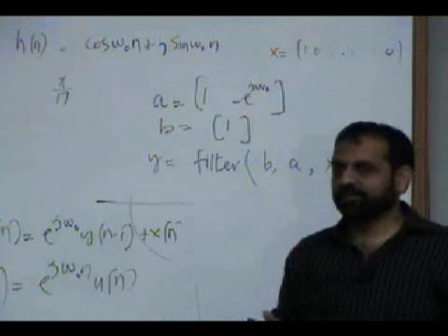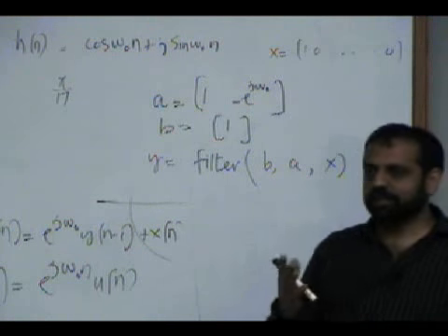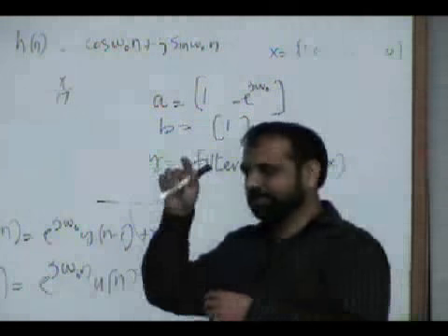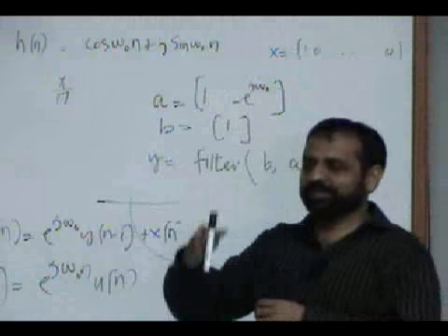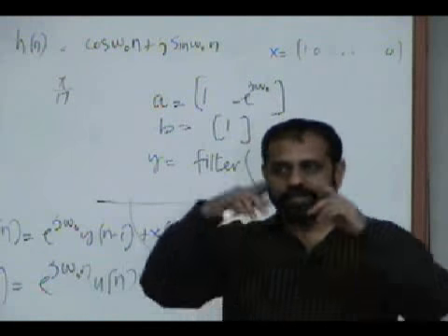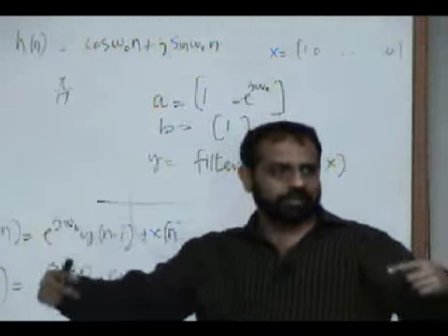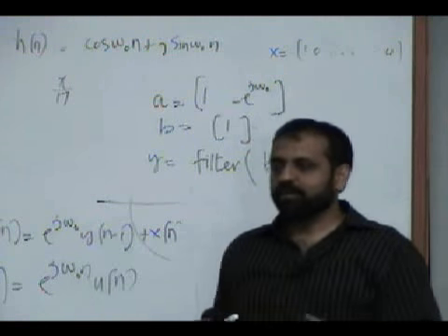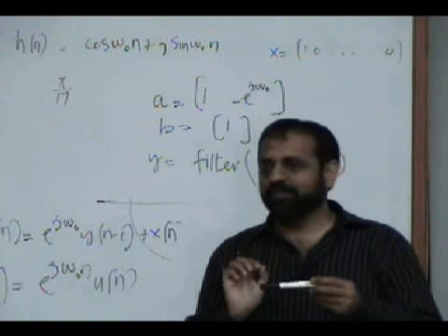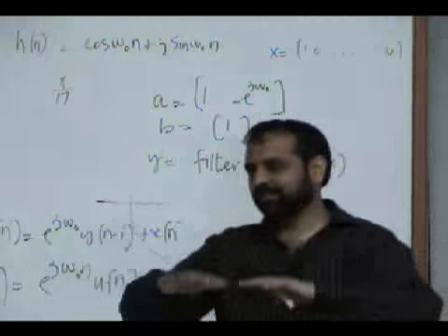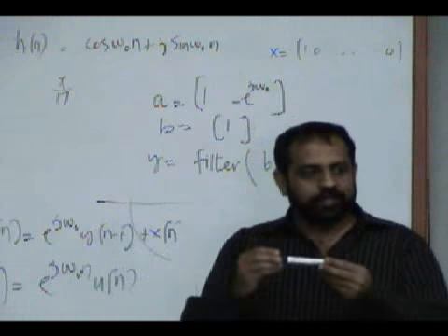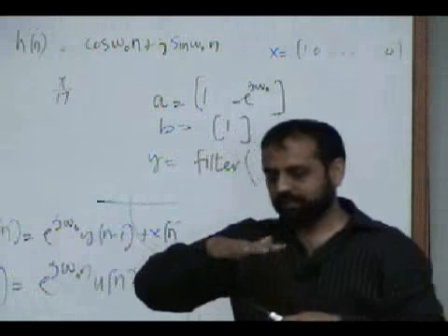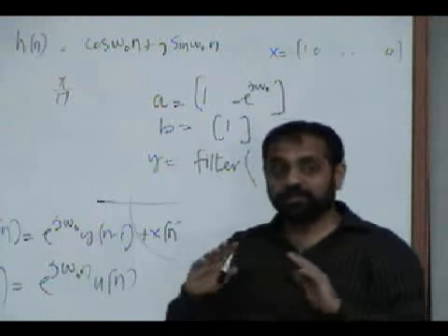This is an oscillator. These tricks are also used in analog circuits. If you want to design an oscillator, you need to place a pole on the y-axis and then just give an impulse. The system will start oscillating. It'll go up, down, up, which is not good if you think of a physical system. An unstable system, if you only apply an impulse, will start oscillating. This is a bad thing. But if it is stable, it will oscillate, and finally, slowly, it will decay down if it is a physical system.